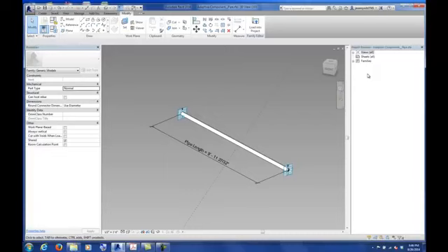It was just already there on screen, and we went from start to end, and it was some distance. When we're working with divided surfaces, remember we divided the surface so that it had equal parts, like 10 in the U direction, 10 in the V direction, and so on. You never know really how big that unit is going to be when you divide up that surface. But now with the reporting parameter, we can extract the information and actually use it so that we can scale things appropriately or do things with that particular element.